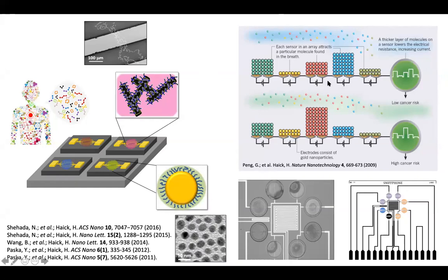On the other hand, you might have another issue. We have other molecules and other chemistries. When they interact together, the film will swell. And based on this swelling, they will increase the distance between the nanoparticles and the conductance will decrease. And of course, we measure a decrease in the conductance. And by that, we can get our sensing signal.